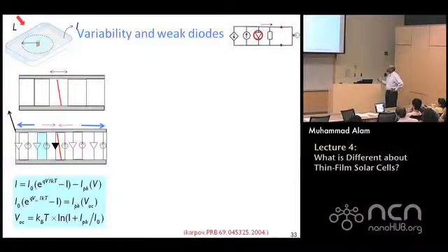Assume that you have a solar cell, and I have divided the solar cell into many pieces, and one of them has a grain. That means all the solar cells have the same characteristics, except I have this black shape. Oh, I should have put, I'm sorry, this is a diode, so this line is missing. But I have a black sheep diode, meaning that diode has a high recombination. So I have marked it black. And so you can easily see that the total current is I, this is the dark current and this is the photocurrent, and V says that it's a voltage dependent photocurrent.